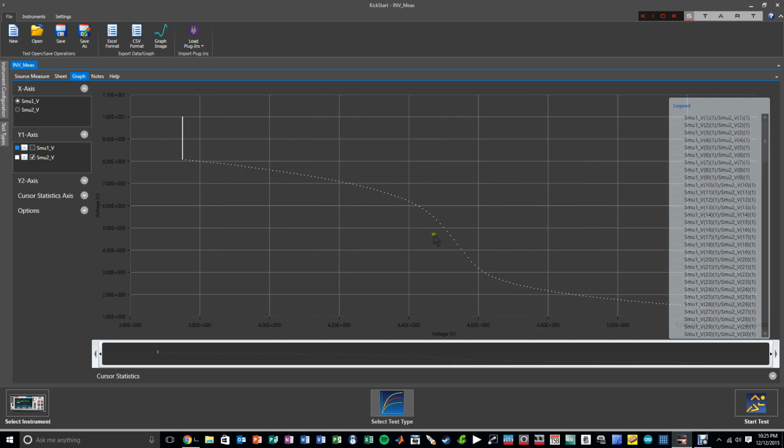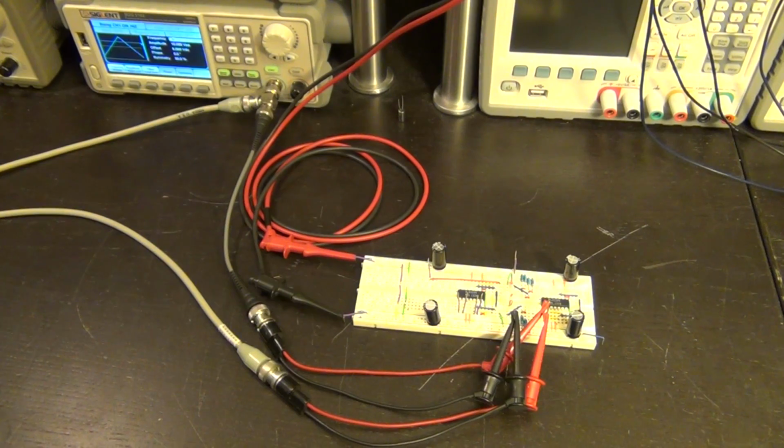But it's difficult to look at it on this software and do analysis on it, so let's grab the data and take it out. Now there is also another way of doing this measurement, instead of having to use the Keithley source meters, but if you want to do it in a transient effect. Now that's not entirely preferred because that is really a transient behavior, not a DC characteristic, but if the frequency is low enough and the inverter is fast enough, it is a good approximation.